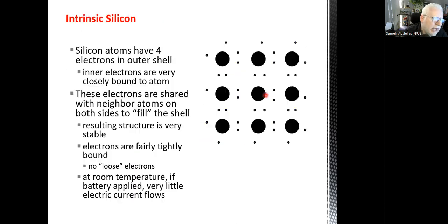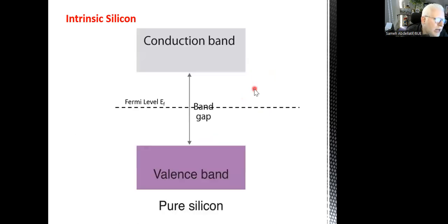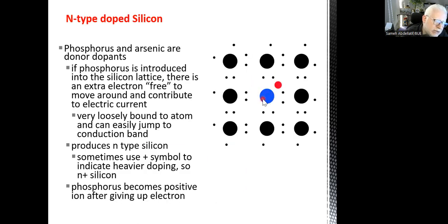So, in the old scenario, this silicon atom has 4 electrons, which, as we said, have a covalent bond with 4 neighbors. Now, the new material, this one in blue, has 5 electrons. So, 4 of these 5 electrons will have a covalent bond with 4 neighbors.